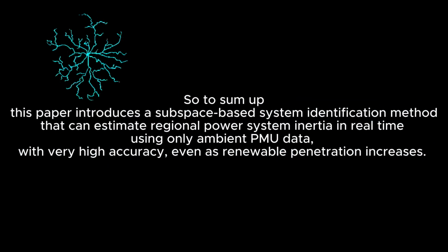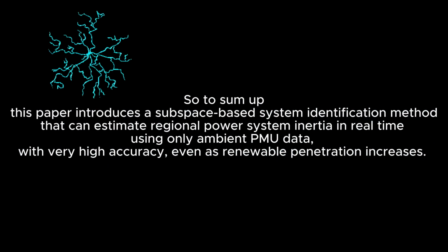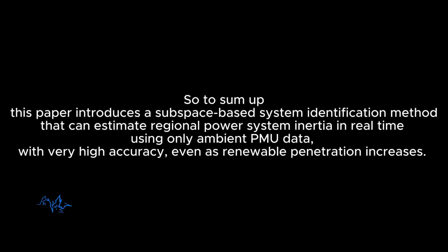So to sum up, this paper introduces a subspace-based system identification method that can estimate regional power system inertia in real time using only ambient PMU data with very high accuracy, even as renewable penetration increases.